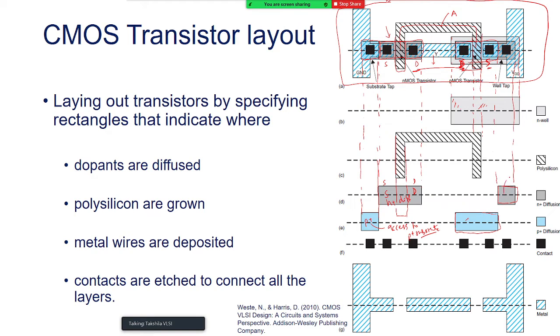So this is giving me access to the N-well, because this region is the body of the PMOS and this region is the body of NMOS. So we know that in the schematic representation, this is drain, this is source, this is gate, and the body I will show like this, which is tied to source. For the PMOS, I know it is shown by the bubble. So this is source, this is drain, this is gate, and the body I am tying to source again. So I will show symbolically this is NMOS and this is your PMOS. So that's why we create these regions right over here. And once that is done, everything is done.